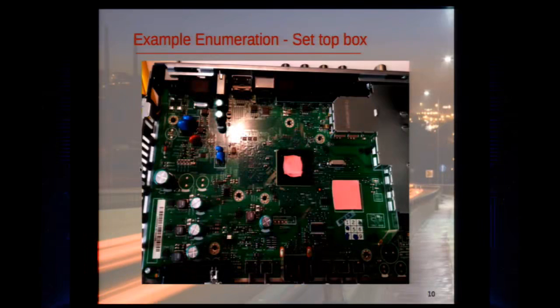And finally, we have this set-top box, which I was way more than a little ambitious in trying to poke at. Just as an example enumeration, we have our external crystal right here on this unknown die, which would have definitely complicated things. And over right here, we have a voltage regulator, which may or may not be wise to attack on this thing, seeing as it draws about 200 milliamps from what I measured.